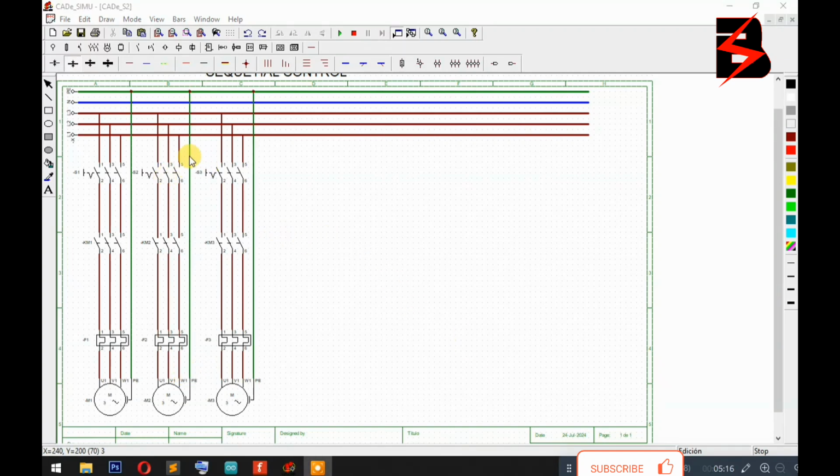After the power line, let's do the control. I'm going to get here my control breaker, that's 2-pole. Then I'm going to have an emergency switch. Before the emergency switch, normally closed of the overloads, and here we use all the 3. This one shall represent all the overloads, but you have to use each. Then this one, I'm going to use it as a stop. Then I'm going to get a normally open to act as a start.